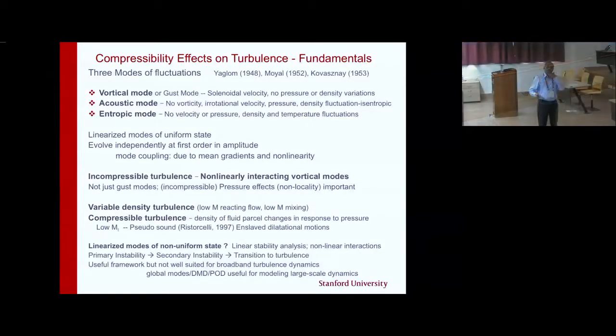Well, let's think about compressible turbulence by contrasting it with incompressible and variable density turbulence. Incompressible turbulence we can think of as strongly nonlinearly interacting vortical modes, the notion of vortical modes now extended so that pressure effects are included. And of course, if you think about a wave space velocity field describing the turbulence, then the associated pressure is very naturally contained in that description. And that gives rise to a non-local coupling, which is a difficulty of turbulence beyond the nonlinearity. Nonlinearity and non-locality being the two fundamental turbulence problems.